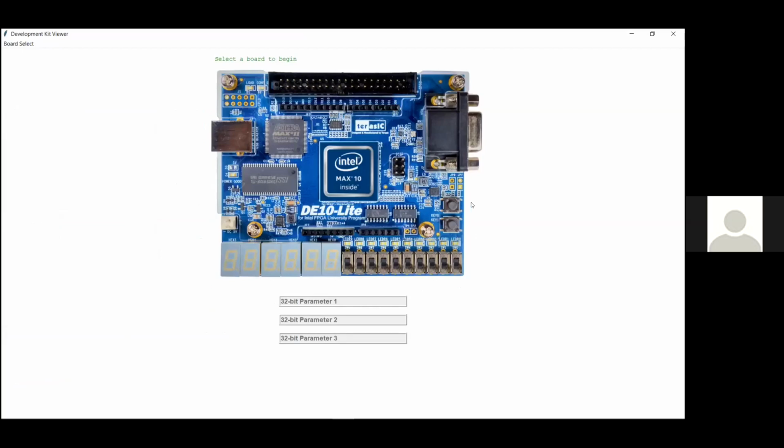So as Larry showed earlier, this is the DE10-Lite board. It's $55. And right now, I have several boards sitting at a remote location with Quartus running on it. My setup is I have a Mac computer with a virtual machine that I've set up as something called a JTAG server, which is software that allows you to host multiple boards on a single machine and then communicate with them remotely.